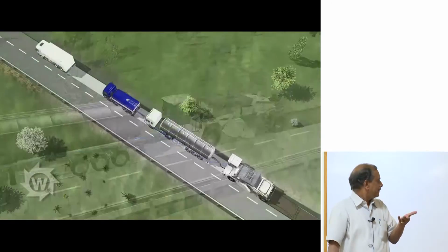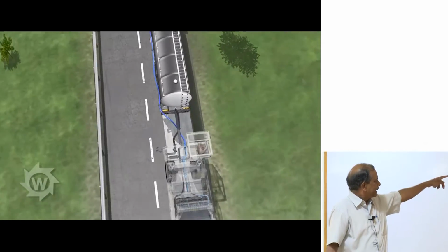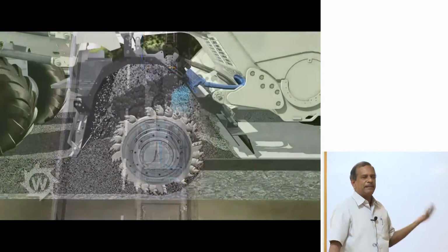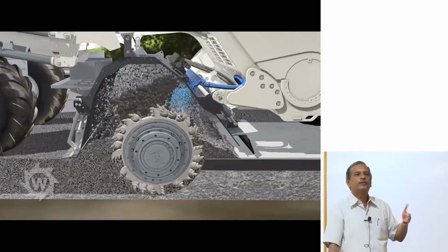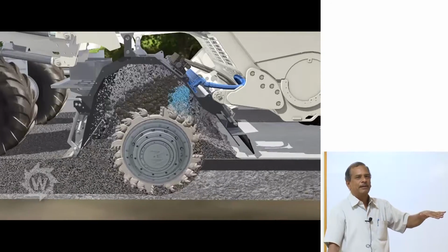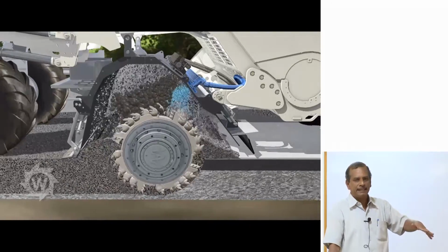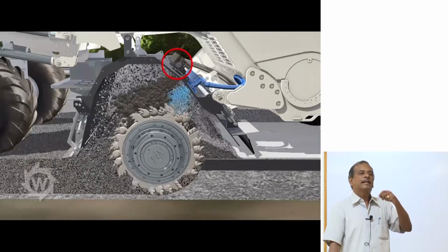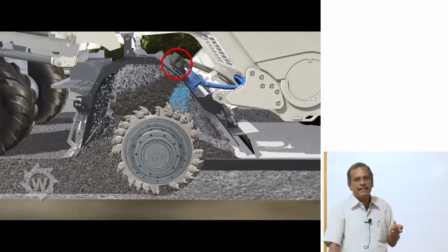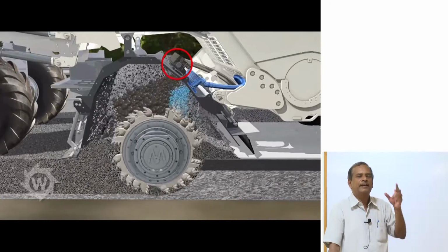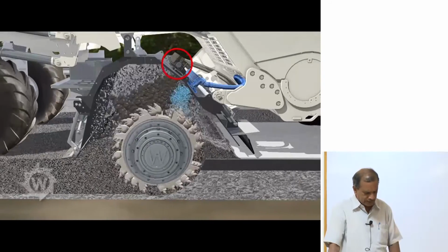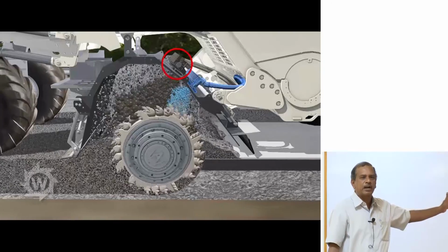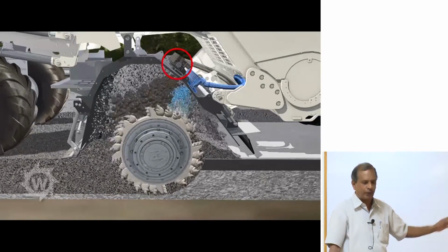I mill the material. I have got a tanker of bitumen. I have a tanker of water. I try to mill the material. To the milled material, I use the foam bitumen and lay it and compact. So, this will result in reuse of the material, stiffening of the aged materials. I try to rejuvenate the oxidized aged bitumen, and by the process I can reduce the thickness of the bitumen layers. So, this is one way of reusing the material, and this technology we have started adopting in several highway projects in the country today.